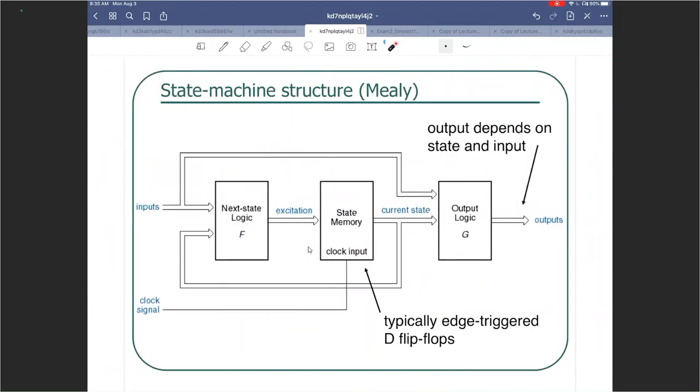Next, let us try to look at the Mealy state machine here, and we'll try to do the same example with Mealy now. So same vending machine with Mealy. Now if you see, you have your inputs all the way to the left, like the nickel or the dime and the reset, and outputs are all the way to the right. That in our previous example was a mechanism to trigger a motor that releases an item.